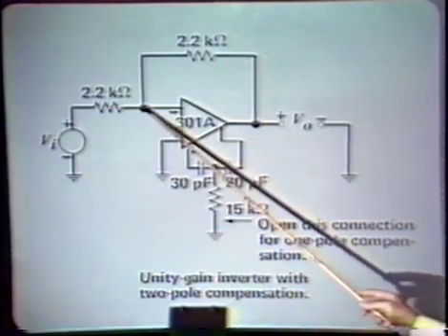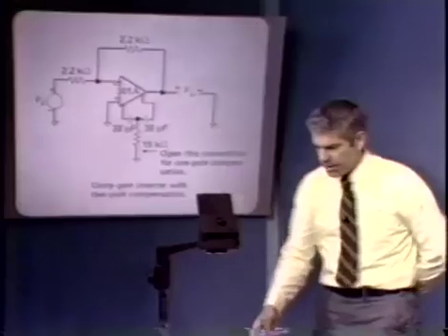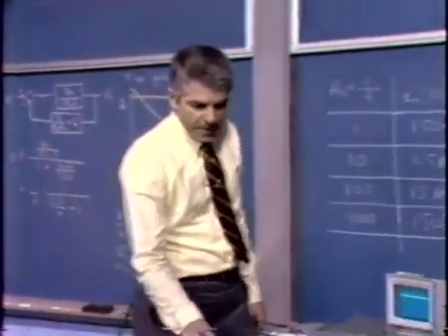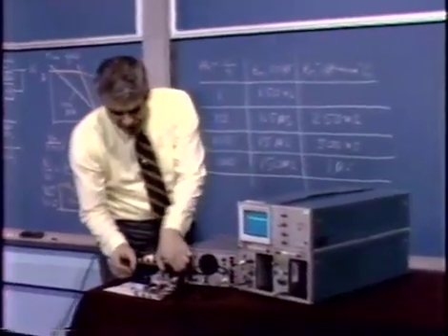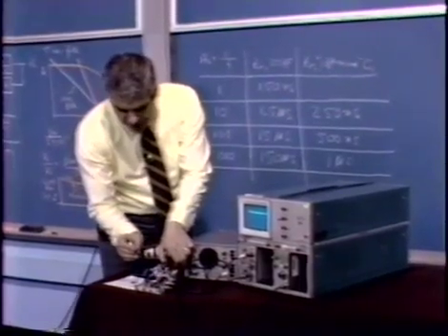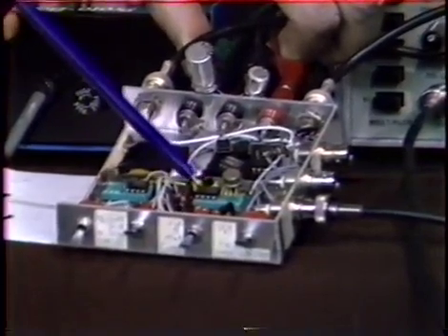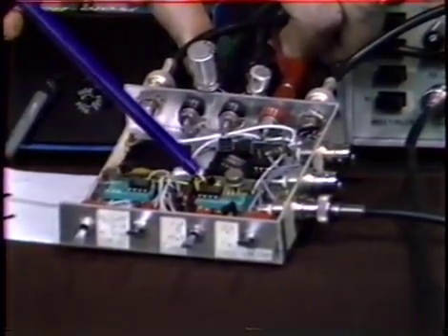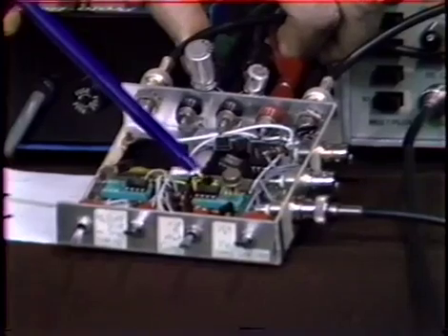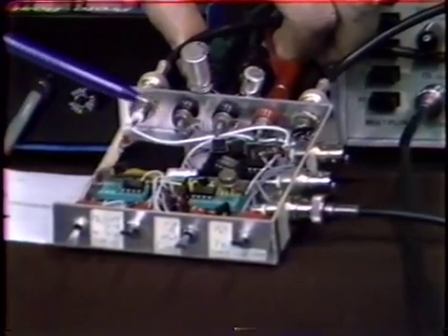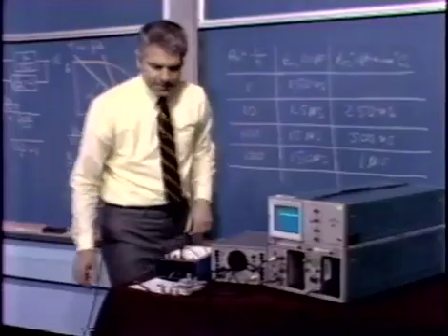And so this configuration allows us to readily look at the error of the system, and that's the reason that we use it in preference to the non-inverting configuration. So, as I say, we have that amplifier here. We have a buffer amplifier that allows us to look at the error signal and present that signal on an oscilloscope when we wish to. And we're able to very quickly change from 1 over s to 1 over s squared compensation, maintaining crossover frequency by simply lifting the resistor in the middle leg of the T.